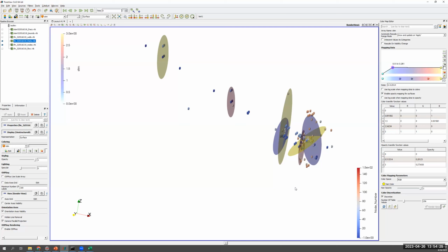So if you flow too slowly, you will underproduce from the reservoir because the heat production rate that you're getting is going to be relatively small. The fluid might be very hot coming out, but there's not that much of it. So the total power being produced won't be that good. If you increase that flow rate, you'll get to a point where there'll be an optimum amount of power being produced, like getting the most amount of power you can over the lifetime of that project.